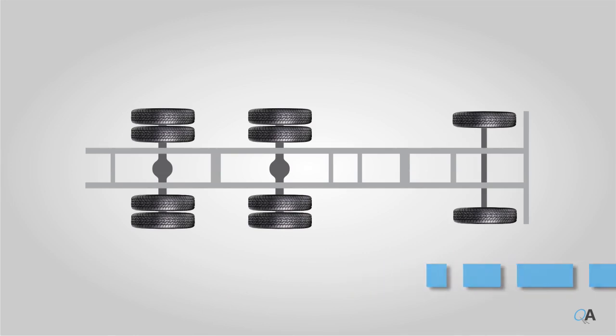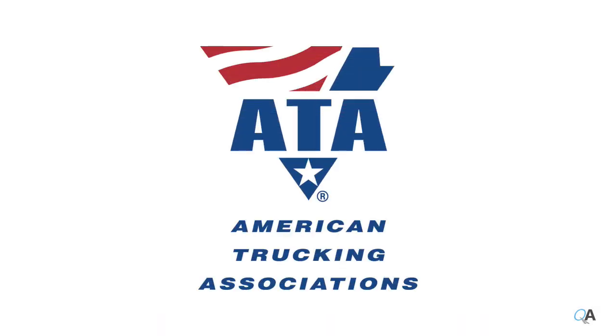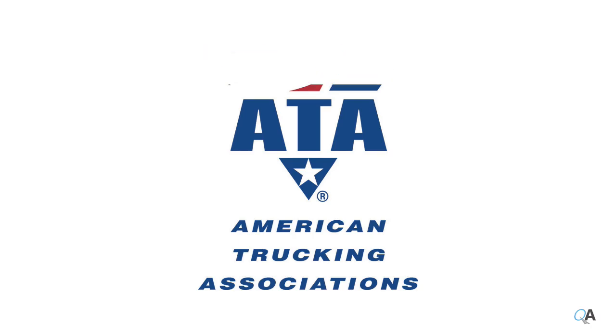In reality, there are always discrepancies between the ideal geometry and the actual geometry, which can reduce the performance of the vehicle. Even subtle alignment discrepancies can dramatically reduce fuel economy, handling, and tire life. It is for this reason that the ATA Technology and Maintenance Council has specified tolerances for alignment geometry in their recommended practices RP 642 guideline for total vehicle alignment.